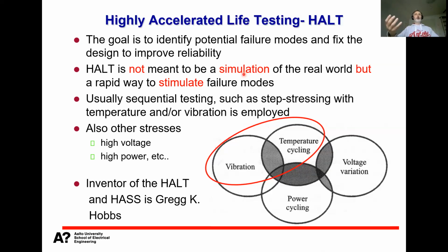Like when we have organic material, plastics like that, they become brittle when the temperature goes clearly below zero, and then they are very sensitive to mechanical load. So that is what we are utilizing in this kind of HALT testing.